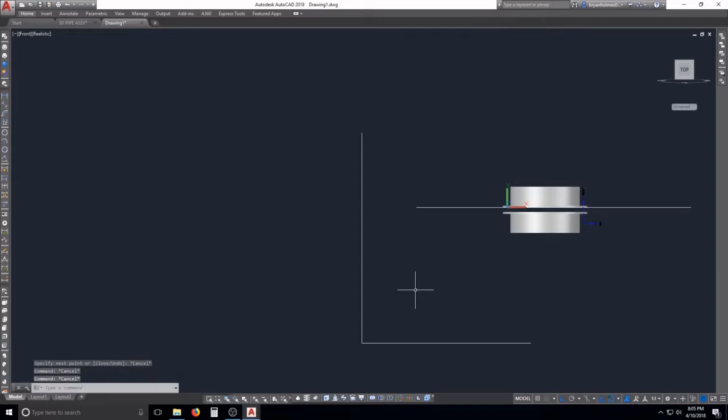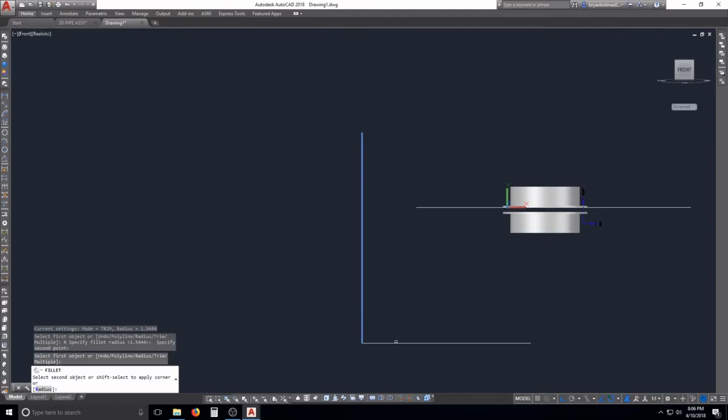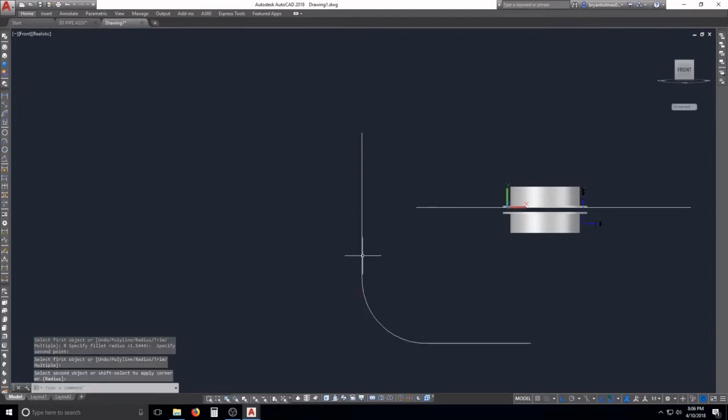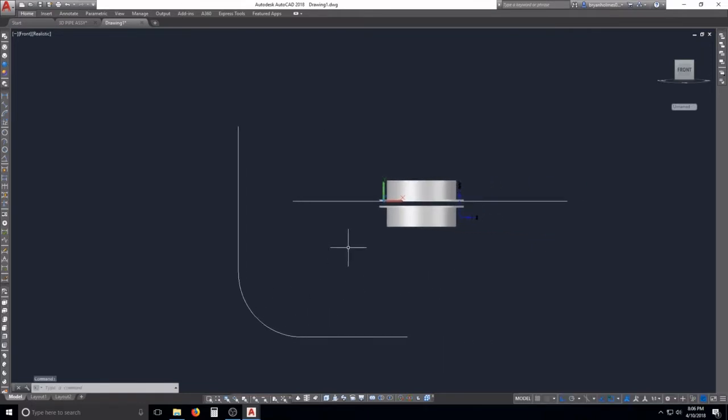Something like that. And to create a smooth transition, if we keep this like this, the light will bounce off it in such a way it just won't look clean. You kind of want to make it like a sheet was draped over it. So what you want to do is create a relatively large radius here. So F enter, R enter for radius, and then just do something like that. See, now whenever the light shines on it, you won't be able to tell where the actual corner or midpoint of that is, just because it's a curve. Little trick I found out a while back.